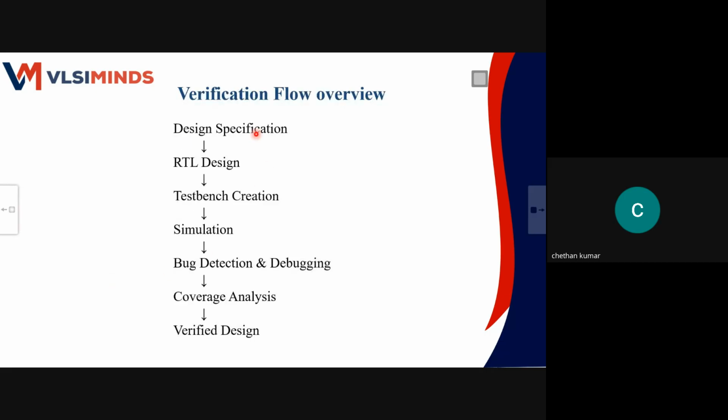And what is the verification flow overview? That means what is the flow of it? So once you get the design specification, design is going to be done. Once the design is done, it will be given to the verification engineer. Now, what he has to do? He has to build up one component. That component we call it as test bench. So through this test bench, you are going to verify the design.